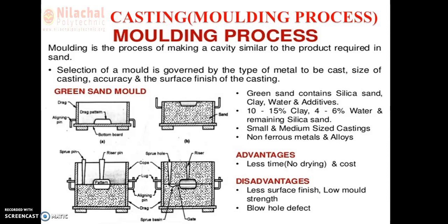The sides of the pit are lined with brick and the bottom is covered with molding sand or binders with connecting vent pipes to the floor level for the escape of mold gases. The cope is rammed over the pit with the pattern in position. Gates, runner, pouring basin, sprue, etc. are made in the cope.